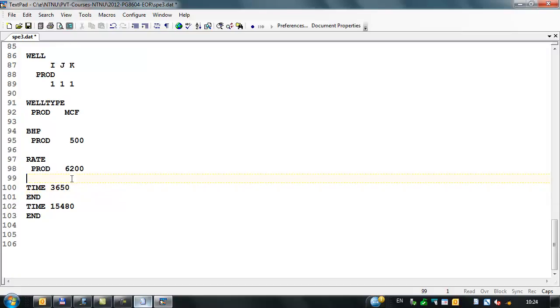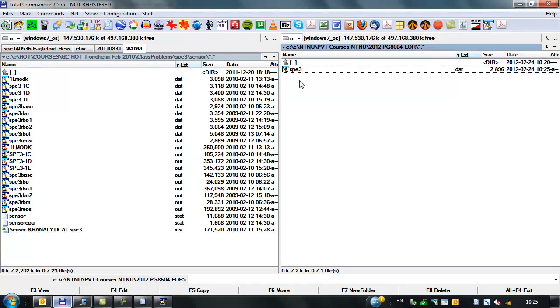In fact, to begin with, we can just stop the simulator. We don't need to run it at all, just to see the initial gas in place and initial oil in place, just the initial gas-oil ratio, because we want to get that to be the same in our PVT program, our simulator. Okay, so I'll just save this, and I'll try to run this data set.